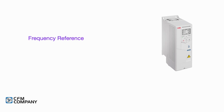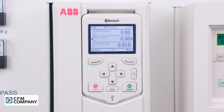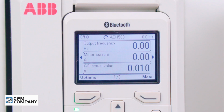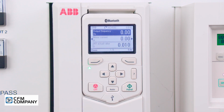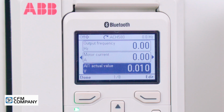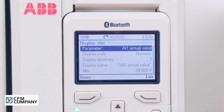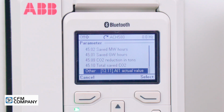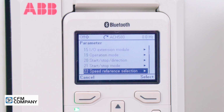When the frequency reference is sent over serial communications, the third line of the display needs to be edited to show the reference value. Use the ACH580 control panel. Press the left soft key labeled Options. Select Edit Home View. Use the down arrow and highlight the third line, AI1 Actual Value. Press Edit. The display slot menu will appear. At parameter, press Edit. Other is shown. Press Select. Use the down arrow and navigate to Group 28 Frequency Reference Chain.